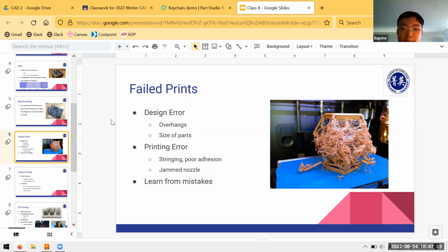You can also have printing related errors due to actual mechanical issues with the 3D printer itself. 3D printers, especially the cheaper ones at the hobby level, are pretty notorious for having issues. It could be something with the software, if you don't have the settings correct, if there is something wrong with the environmental conditions, or your parts are getting old. You might run into issues like the nozzle not getting hot enough.